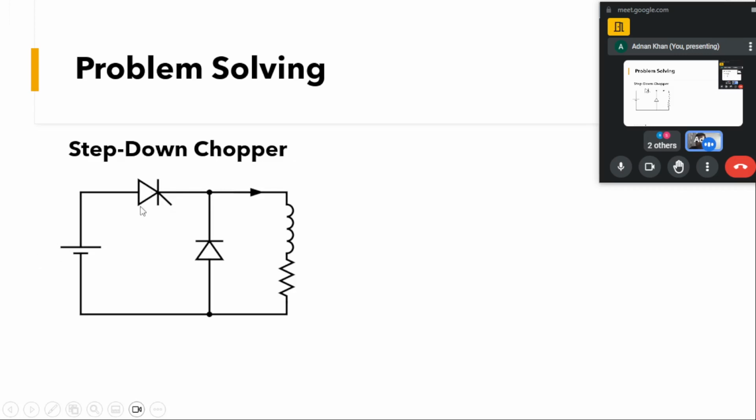So you can see when this device, our control device, is turned on, this voltage will come across this load. Like 220 volt DC will be implemented across the load R. So when this is implemented, this will be our circuitry operation. When a positive voltage is applied across this RL, this IL will start to rise. Like we know VL is equal to L di by dt. When V is positive, di by dt will be positive, so it will start to rise.